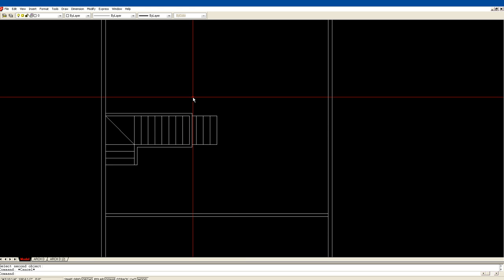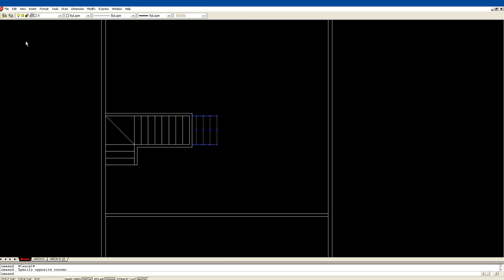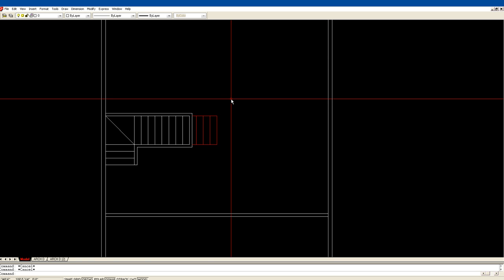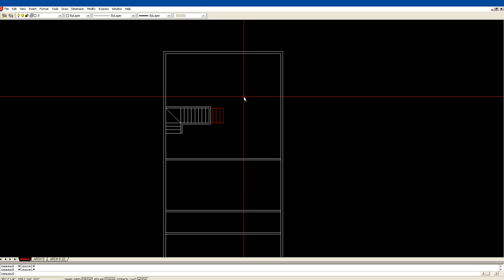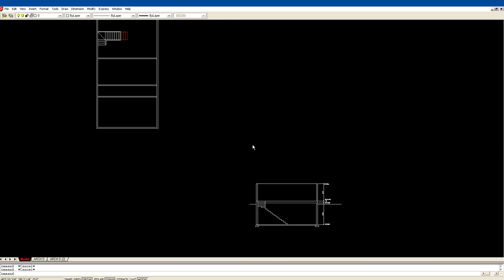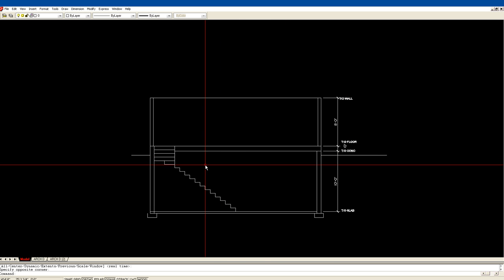Okay, those are underneath. We can actually select them, come over here to our layers, and put them on a hidden layer. So the things that are on layer 0 are walls that we can see when we're looking down a floor plan, and the red will be things that we've accounted for. Okay, we also know that our head height, we've established where that is, 10'8". Okay, and again, we can do it here just as a reference point.